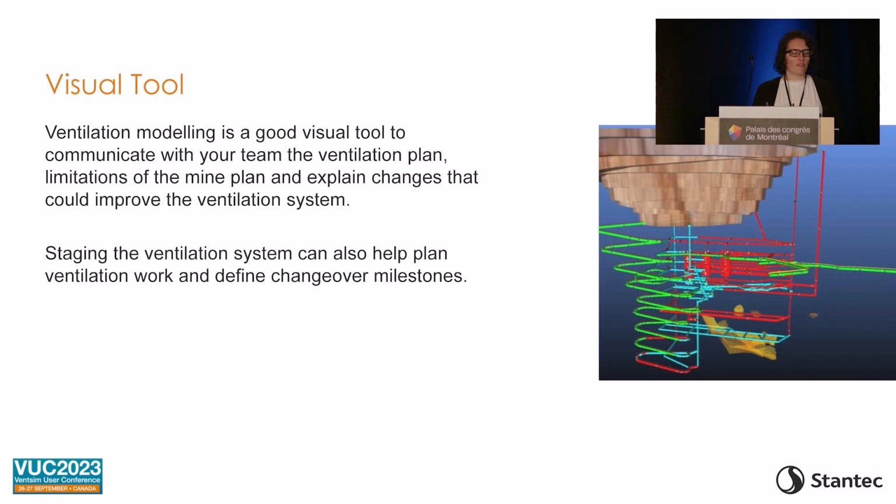The first point I wanted to touch on was using Ventsim as a visual tool. It's very powerful, especially when we're communicating with our teams, because we can show them how the ventilation model works. We come across a lot of mining engineers who are very proficient in mining, but sometimes don't have a clue about what ventilation is. So just showing them with colors, okay, this is an exhaust, this is an intake, it's very helpful, right? And you can tell them why you need a raise, because a lot of times they're like, why do you need a raise? So it's very helpful for us to communicate.